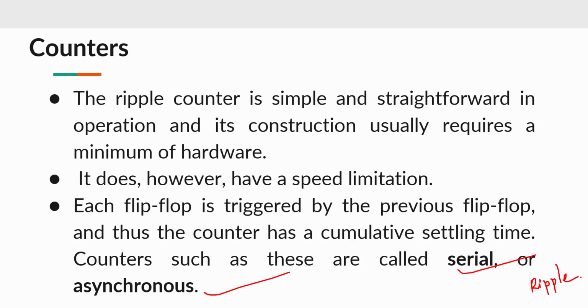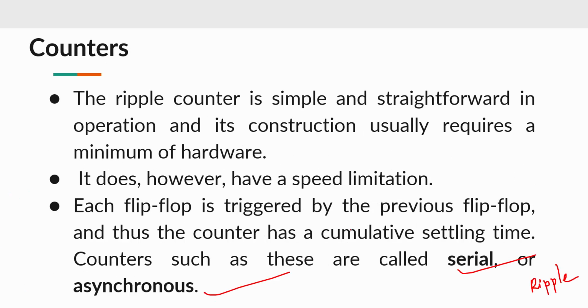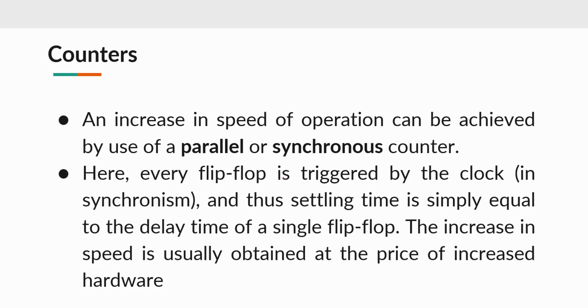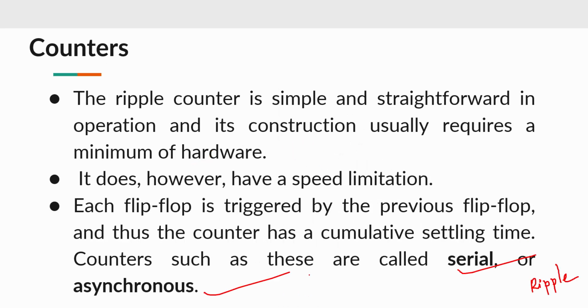Asynchronous counters have one more name, that is ripple counter, based on this implementation. Another counter is the synchronous counter, which we can call a parallel counter. Synchronous counters or parallel counters. But asynchronous counters we can call serial counters or ripple counters.